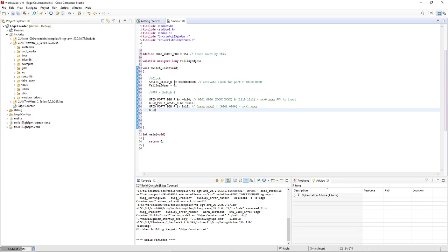Now comes a really confusing register that I still am not entirely sure what to do with, but it's the GPIO port control register. And this register is initialized very strangely, but for this particular example we want to initialize the ones with pin F to 0. So we're going to do the AND, and I'll just copy this because I get this number wrong a lot.